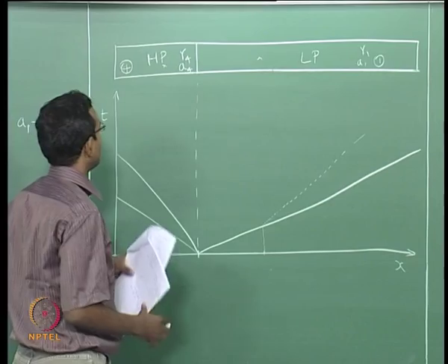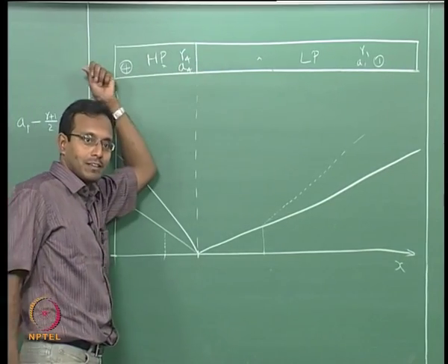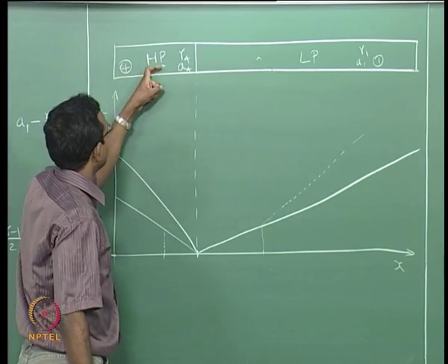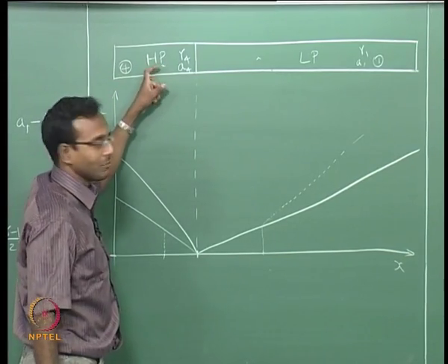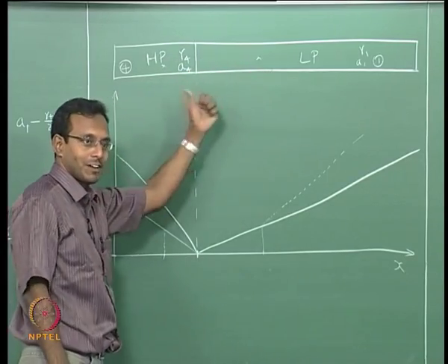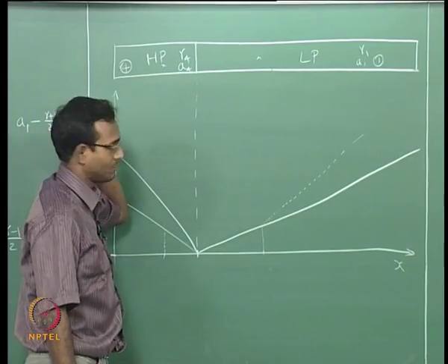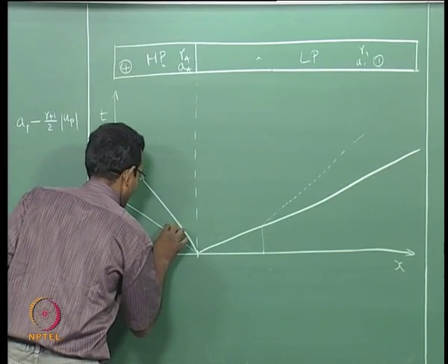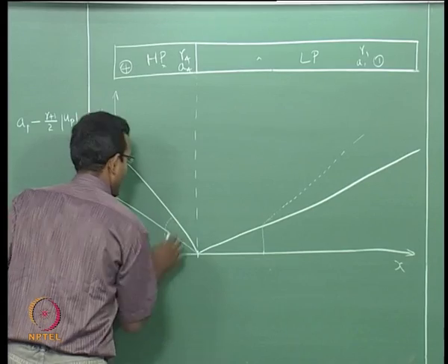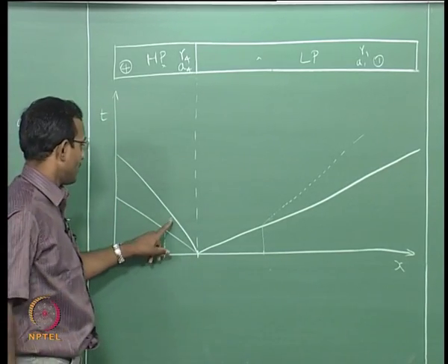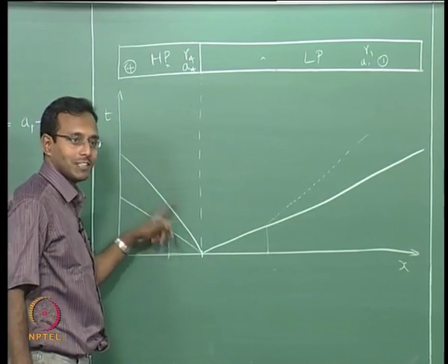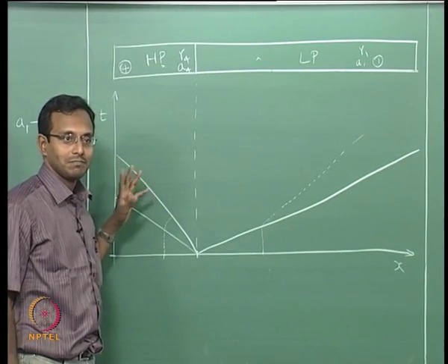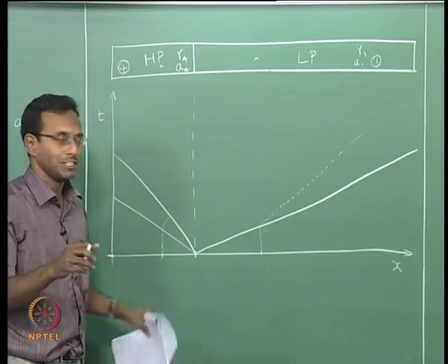After that, since it is an expansion wave coming this way, what will it do? It will induce a velocity in the opposite direction. So this fluid element at that point will want to travel the other way. Expansion fan will go this way to the left, and the fluid element will want to go to the right. So it will start going to the right, and it will keep on accelerating towards the right only up to the last expansion wave. After that, things have come to equilibrium, it does not want to change anymore.